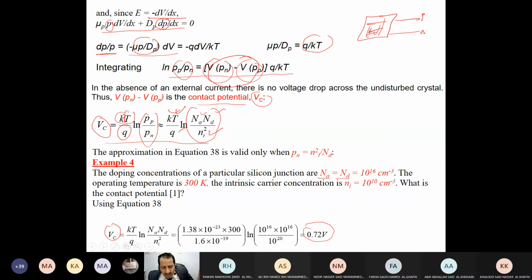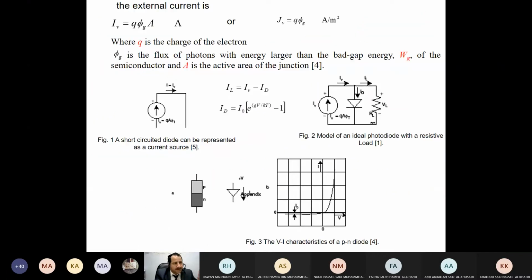I would like to talk about this number. Have a look and make sense of it. The voltage across the terminals of a solar cell is in the range of 0.7. If it is lower, 0.6 or 0.5, this means that the quality of the cell you are using is not good enough. Usually the standard is 0.7, and this is what is mainly available in the market. Plus or minus is okay, it's fine.